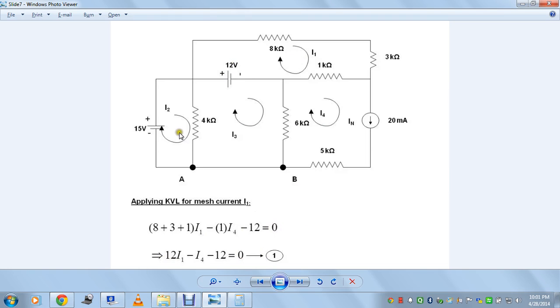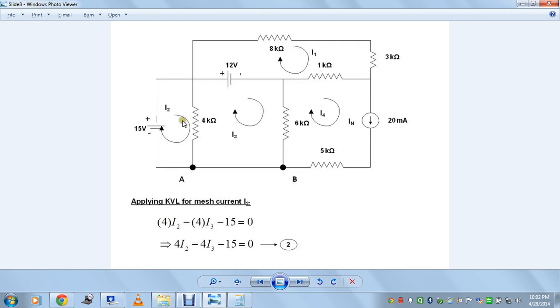Similarly, we'll be having 4 equations for 4 unknowns. We'll see the same for the mesh current I2. I will explain that also, so that it is more familiar to you for assigning signs for the voltage drops and developing mesh equations very thoroughly and making it simple for you. I will explain all the meshes right now. So for mesh 2, applying KVL for mesh 2, what we have here is the current I2.